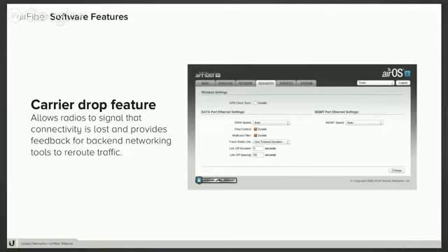The typical case you'd see this used for is that it would simply track the RF link up and down. Right now we've added a feature, displayed here, where we're saying use timeout duration. We are dropping the link, but we're not going to drop it for as long as the radio link is down. We're just going to drop it for 5 seconds, and then we're going to leave it up for the next 85 seconds.